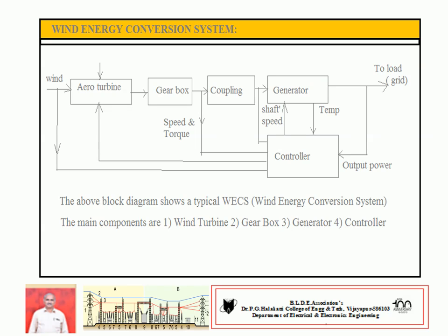If less wind is available, then also the system should be off, because wind generation will operate for a particular range of wind speed only. At lower speed, it remains cut off. At very high, dangerous speed, damage may be caused to the whole wind unit. Hence the generation remains off by using some controller instructions. Hence, you practice all these things.